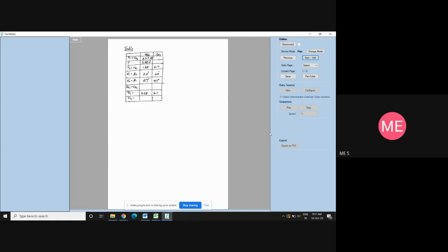Now we'll go for the next step, because this you can get from the figure. What is he asking to find out? First thing is blade efficiency. So we'll go for that as a third step. What is the formula for the blade efficiency? Generally, the blade efficiency is equal to W by energy available. Either you can find W and energy available separately, or you can find work done divided by energy available at inlet.